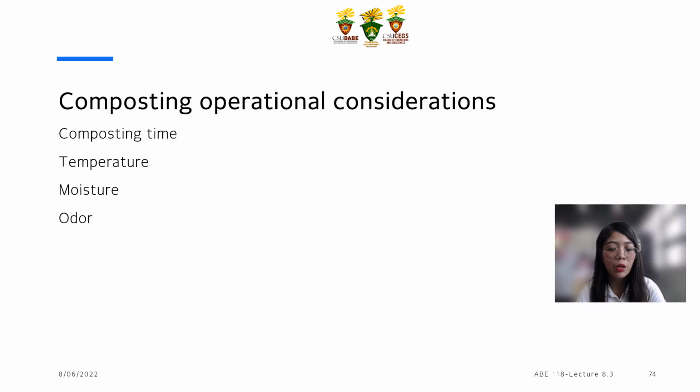And for composting operational considerations, the landowner should be provided a written set of instructions as part of the waste management plan. So these instructions should be detailed, and the operation requirements are necessary for successful composting operation. They should include the compost mix design, the recipe, method or schedule of turning or aerating, instructions on monitoring your compost process, and the long-term storage of compost.